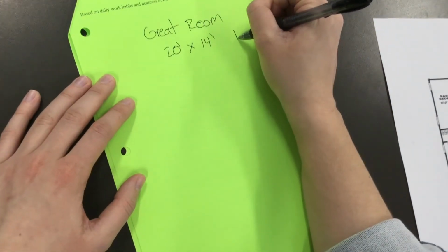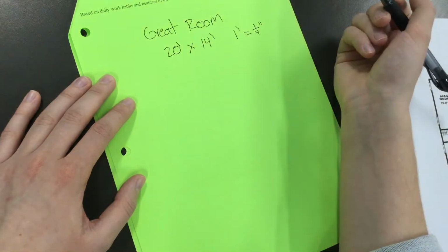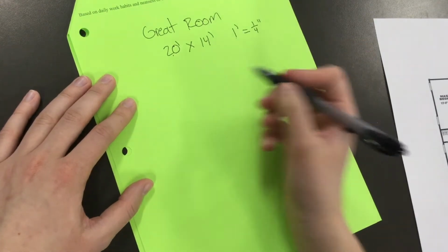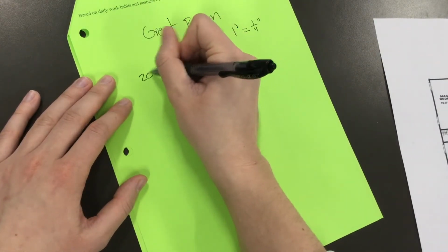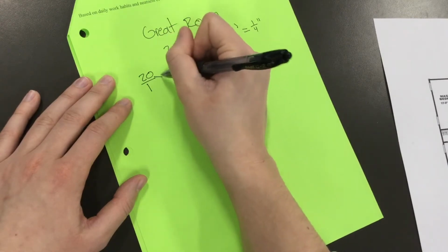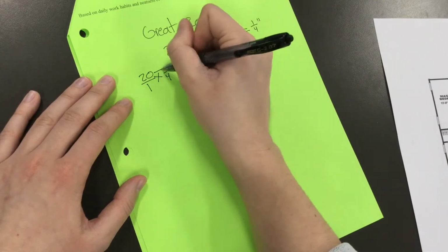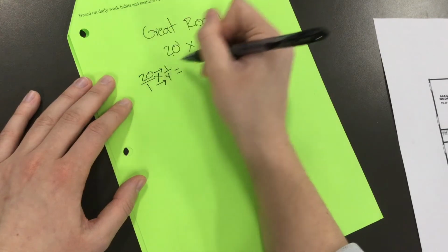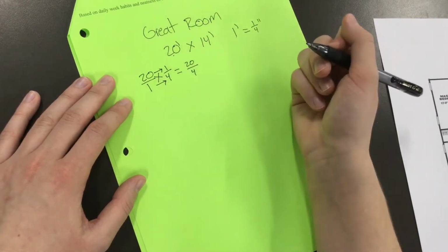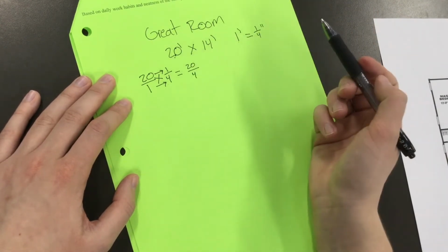So our scale is 1 foot equals 1/4 inch. Which basically means I'm going to multiply my feet by 1/4. So if I take 20 feet, if it's a fraction, we need to multiply it like a fraction, multiplied by 1/4. Which, when you multiply fractions, you just go straight across. 20 times 1 is 20. 1 times 4 is 4. So I need 20 quarters. You could have jumped straight there and gone, I need 20 of these quarters.